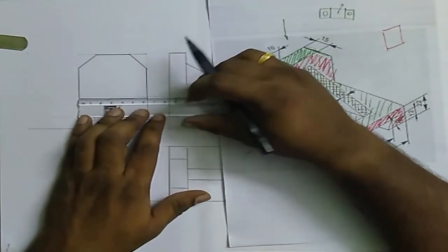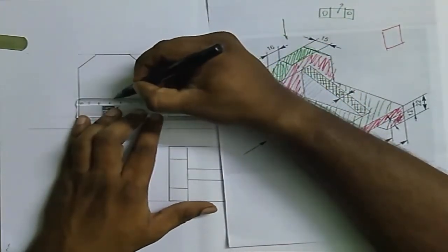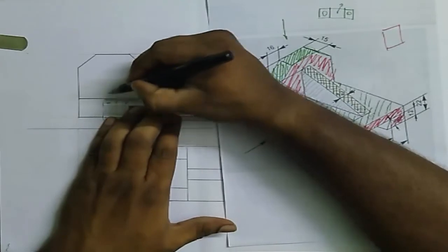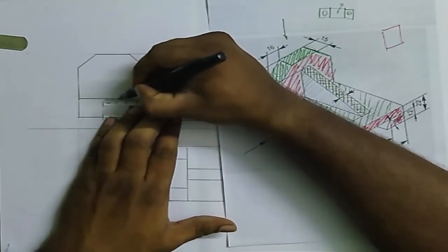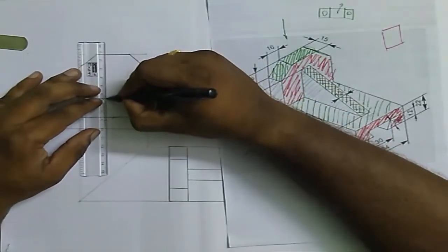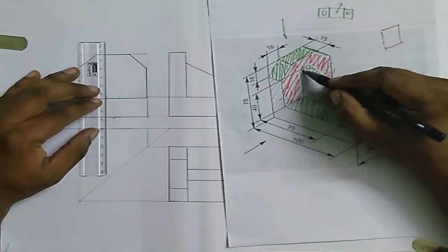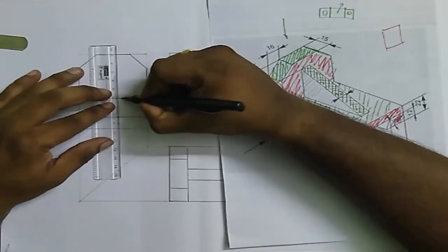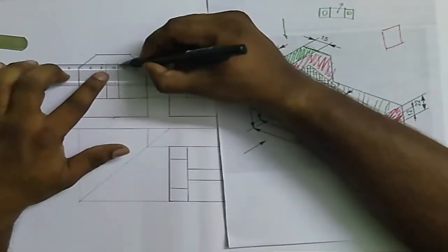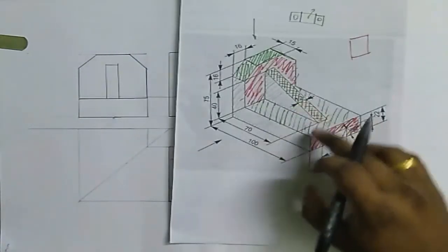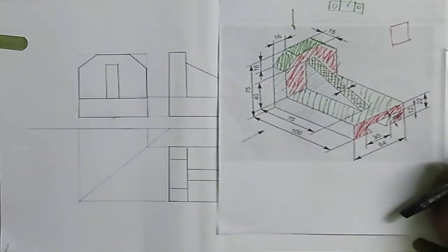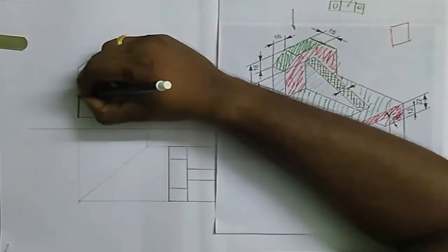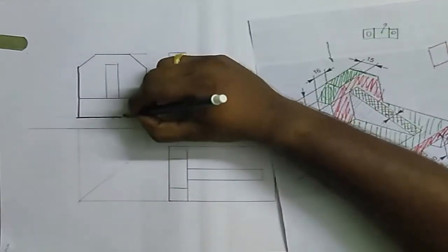Then you have to draw this line, that is this line will be viewed from here. So at the center point of 64 mm, that is 32 mm, the thickness of that is 6 mm. So from this point make 6, 6, so that you will get these 2 points. The height of this line is 40 mm. So from here make a 40 mm line to here and also from here make a 40 mm line to here. So close this line, you will get this surface also. This is your left hand side view. So then all these edges can be drawn with H pencil in order to finish the drawing.